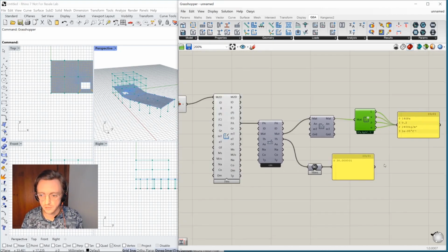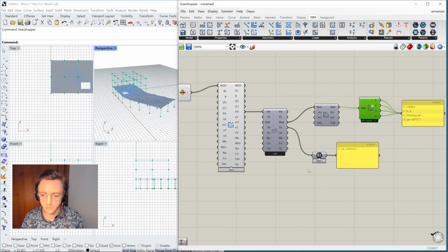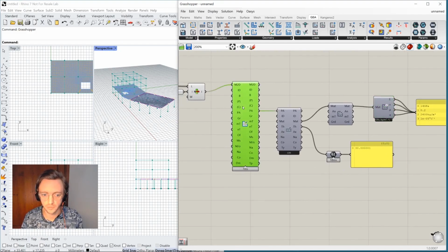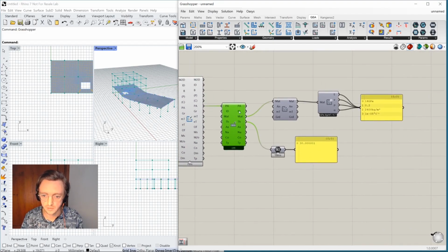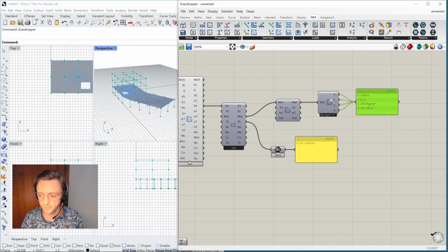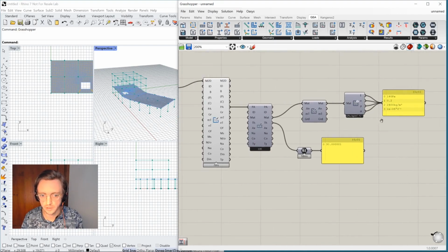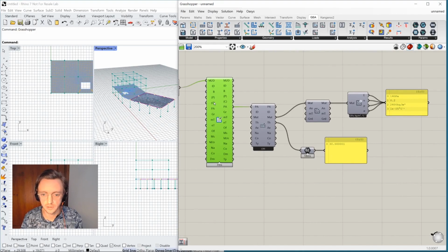That was a quick introduction to getting more detailed information out of an existing model. So we took one 2D member out, and we could see that inside this object we have different layers. We first have a 2D property. Inside that 2D property we can get the thickness, and we can also get the material. So in another layer we have the material, and from that material we can get the material properties belonging to the top level 2D member.